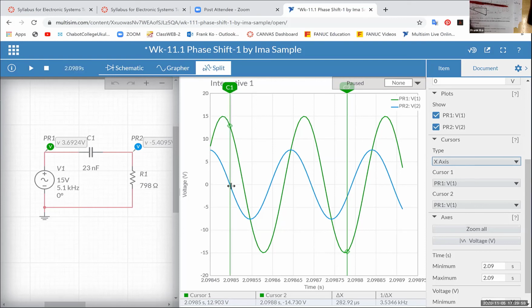focus your attention on the zero line and the blue waveform. Where the zero line right here and the blue waveform meet, I want to intersect that with my cursor number 1. Best as you can eyeball, move this back and forth gently, and pin it as best as you can, just with your eyeball. Okay, and let's pin this one right there.